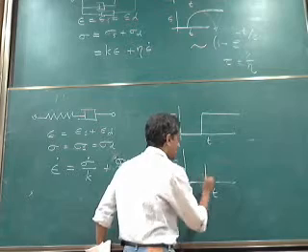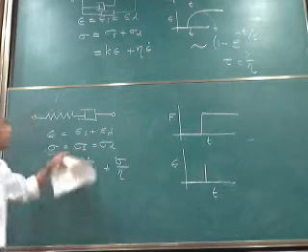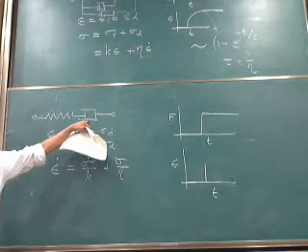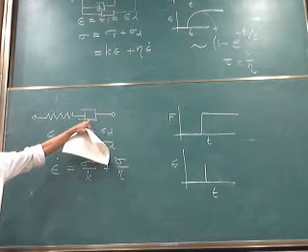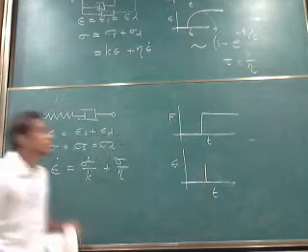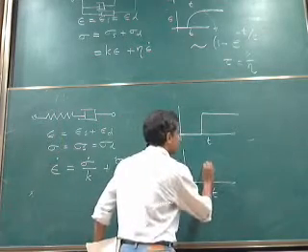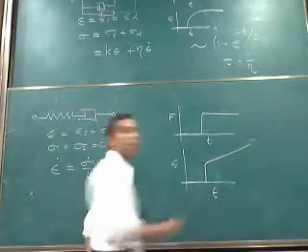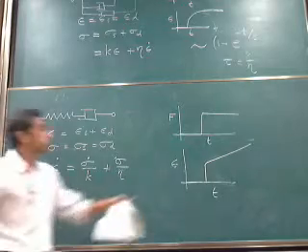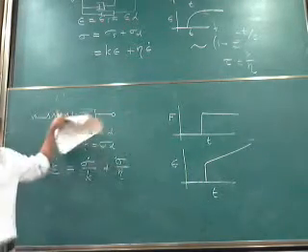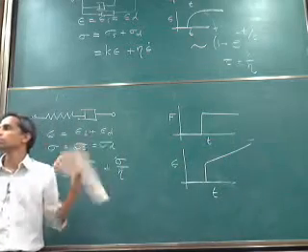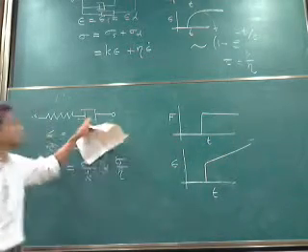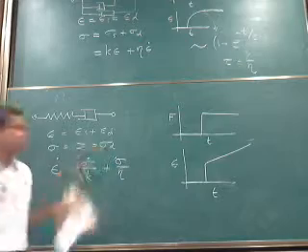So this element will first stretch instantaneously, and then what will happen? There is a viscous element here. So there is no equilibrium, and this thing can keep stretching forever. After the initial stretch, it will go to this. This initial stretch will give you a measure of the spring constant, and the slope will give you a measure of the viscosity, because at long times it is only the dashpot which is contributing.